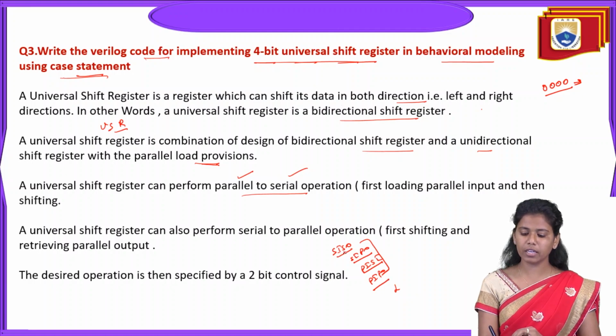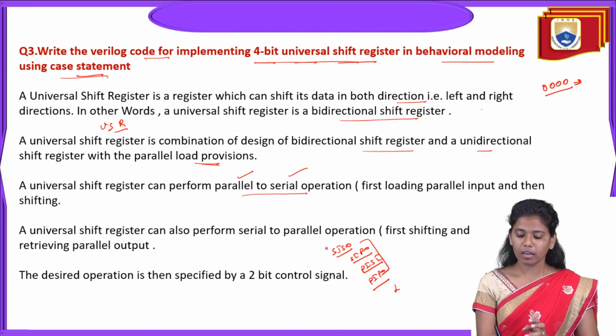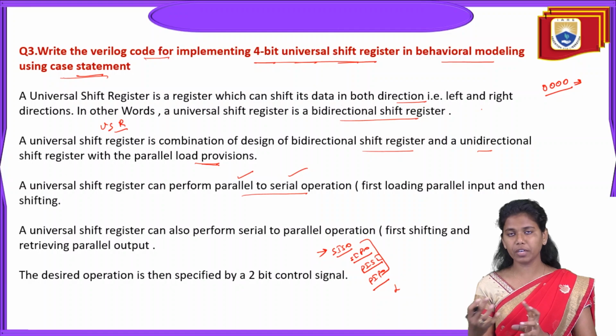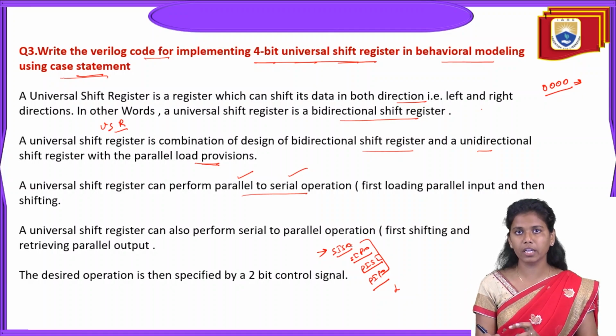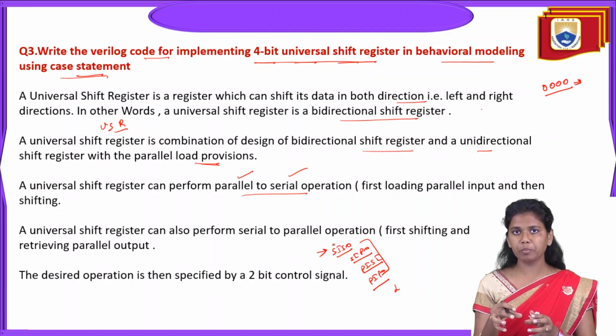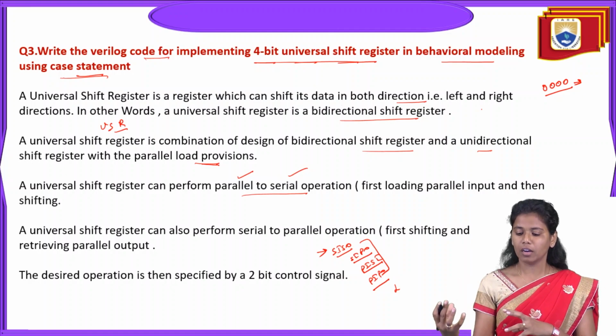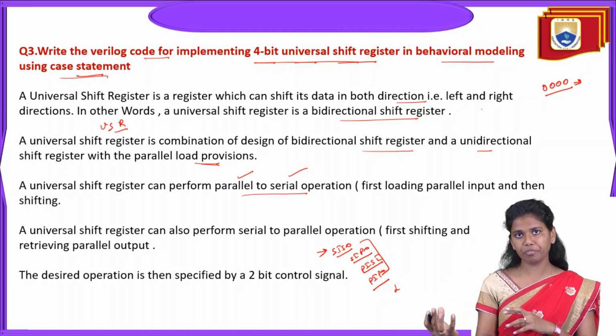So what does serial in, serial out mean? It means that the bits are serially loaded first, and then they are shifted serially. At the input part it is loading serially, and at the output part they are just shifting the bits.